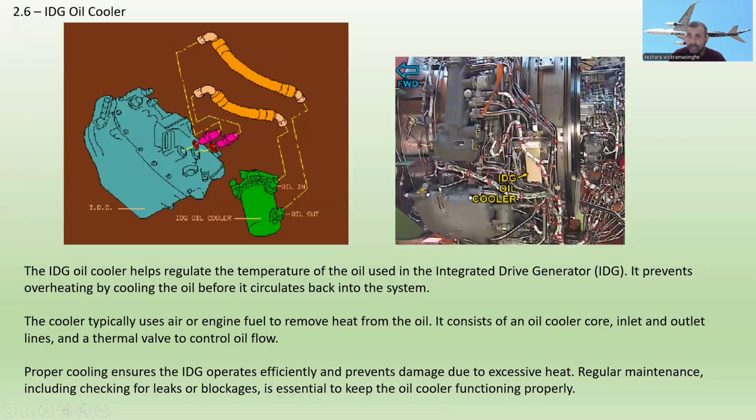The IDG oil cooler is not situated near the IDG, but is situated in the fan, near the fan cowl, on the left side. So this is the IDG oil cooler. The oil cooler is situated here. Okay, this is the IDG. It comes with two connections, right?